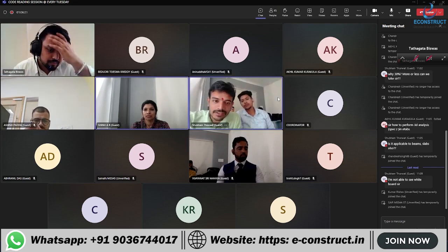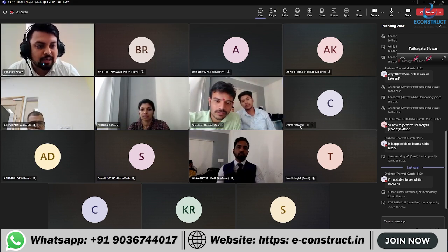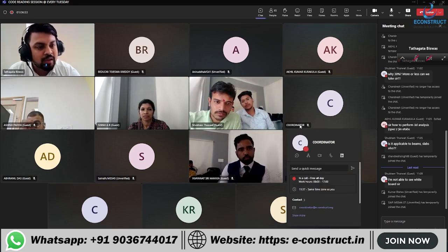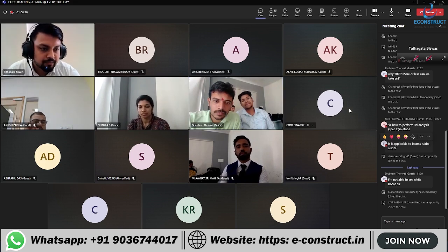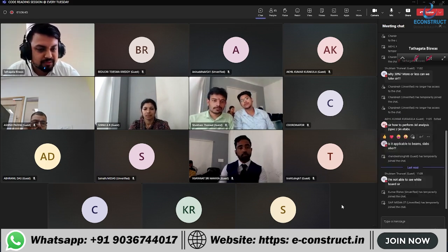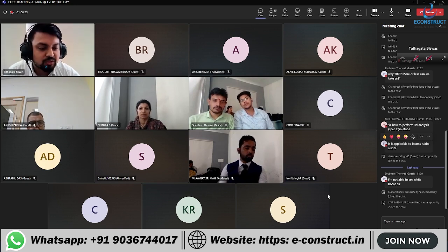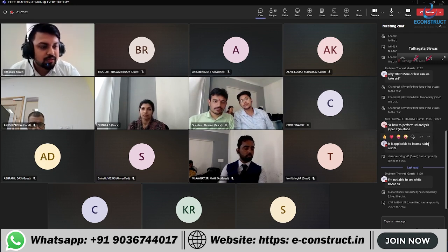Sir, is the 130 applicable for beams also, or what? No, 130 is only for columns. For that particular floor, actually, if it is fully non-orthogonal, but generally column will be predominant for the design changes. You will hardly get some changes for beams and slabs. It would be hardly something. So if you're taking that, not taking that doesn't make any difference. But in columns, yes, because their axis only gets changed completely in terms of global axis that way. Yes, beam slab would also have certain very, very nominal changes, but yeah, that is there.